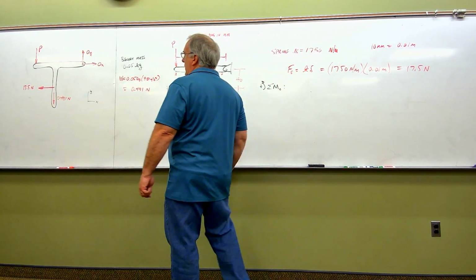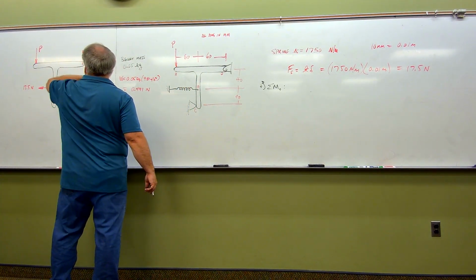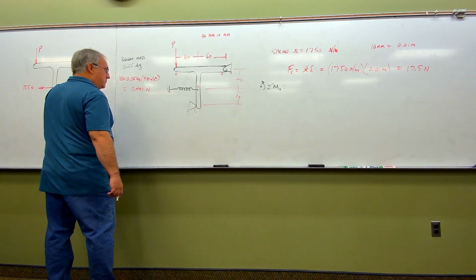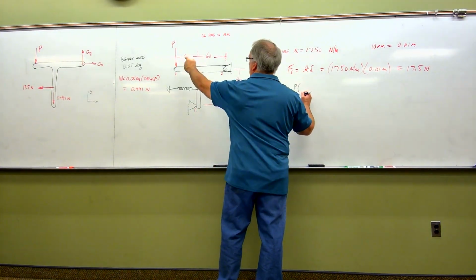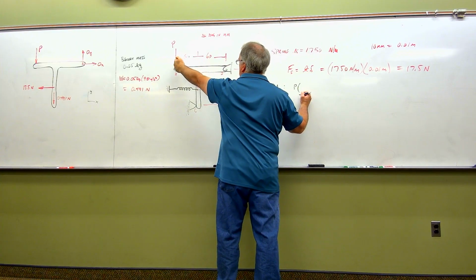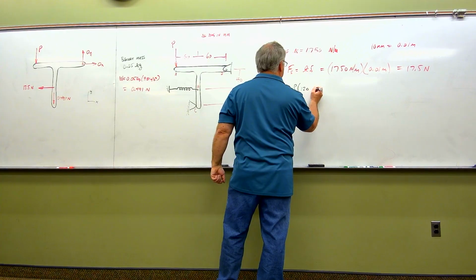And let's see what we got here. First off, I'm going to take care of force P. Force P is causing a counterclockwise rotation about point O, so therefore it's positive. So I'm going to have P times my moment arm here, which from these original dimensions, all in millimeters, from here to here, is a grand total of 120, so P times 120 millimeters.